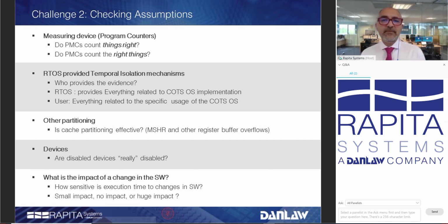The same comment appears with the use of caches. A typical interference channel is because of sharing of caches. So if you have a shared cache and you have processors that are making requests to the cache, the cache contents of a core may be disrupted because cache evictions are being introduced by memory accesses coming from a second core.